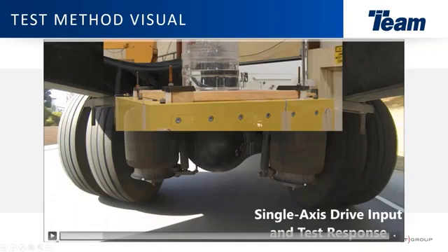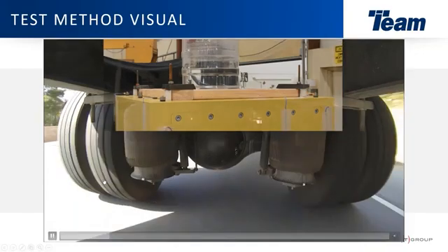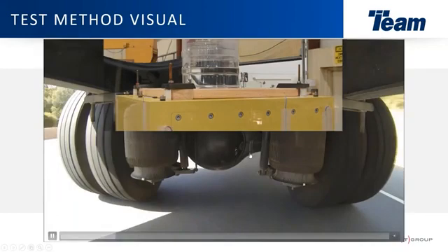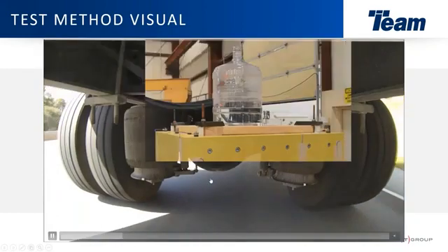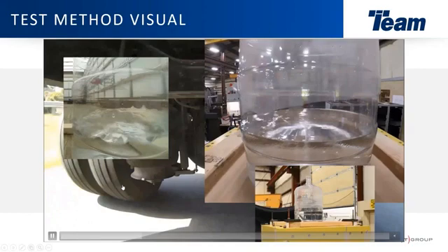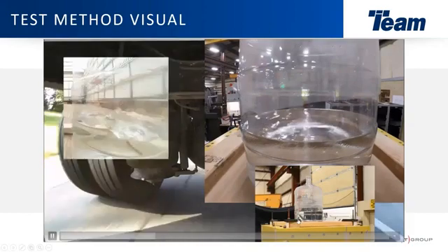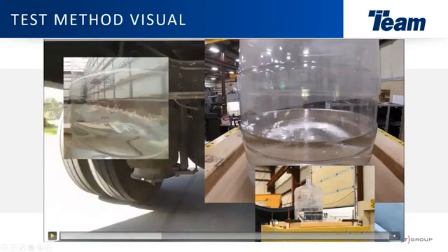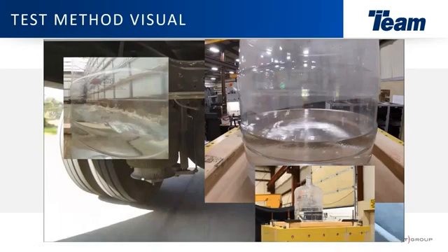So here you can see the input from the road is bouncing around, and replicating this water jug on the same test setup in the lab on a 6-degree of freedom system, this is the cube 6-degree of freedom system here, we're actually constraining out the pitch, roll, yaw, and 2 horizontal axes in order to provide pure vertical motion.